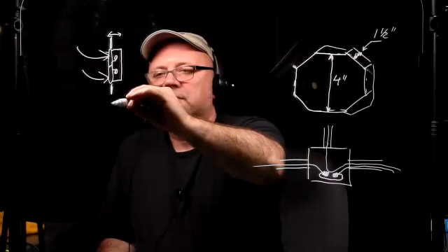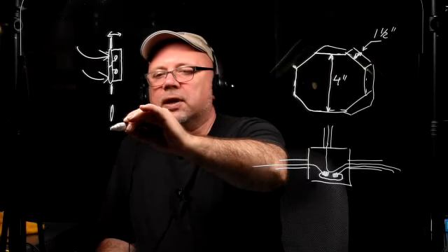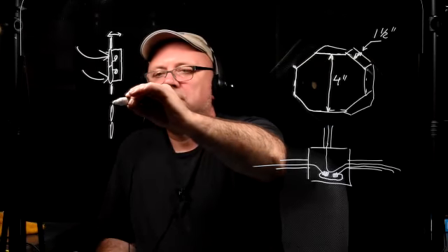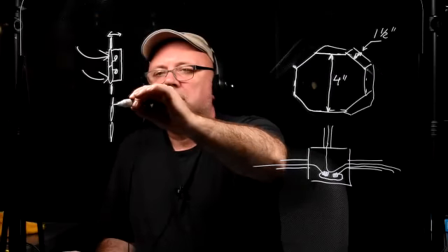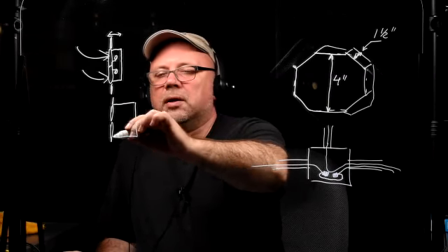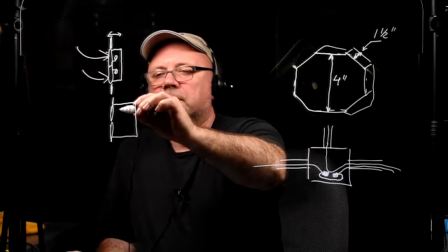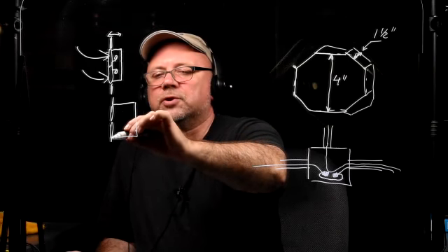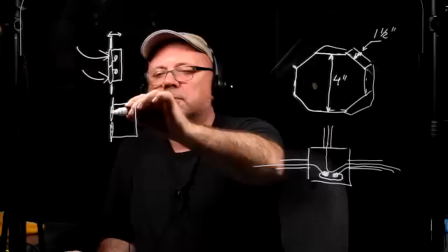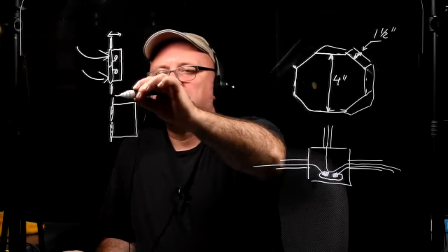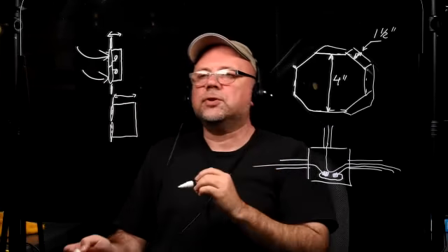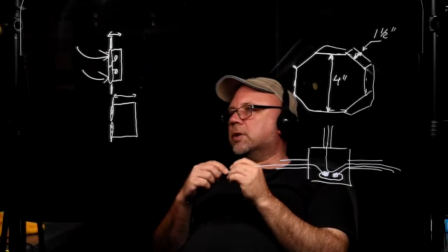That will be the duplex receptacle. Now, if you have the same receptacle, but it's a GFCI, and we'll talk about what that is, that thing is quite deeper because it has to contain some circuitry inside. So it's a deeper device. So you will need a deeper box to accommodate the same amount of wires if you want to use a GFCI.